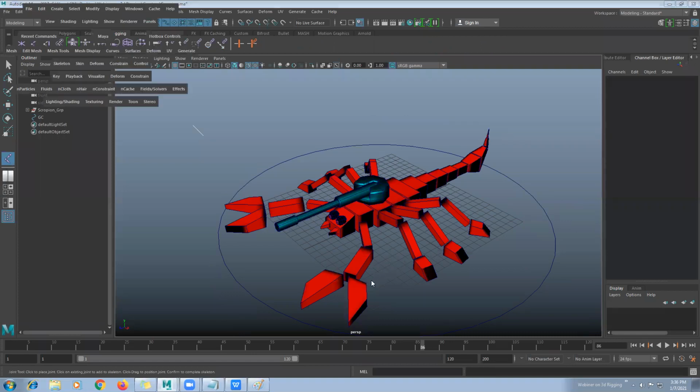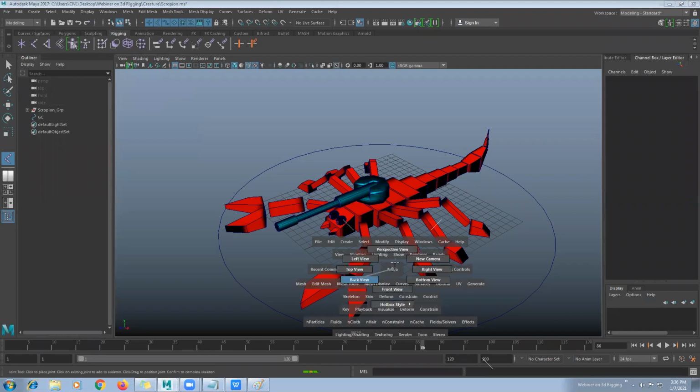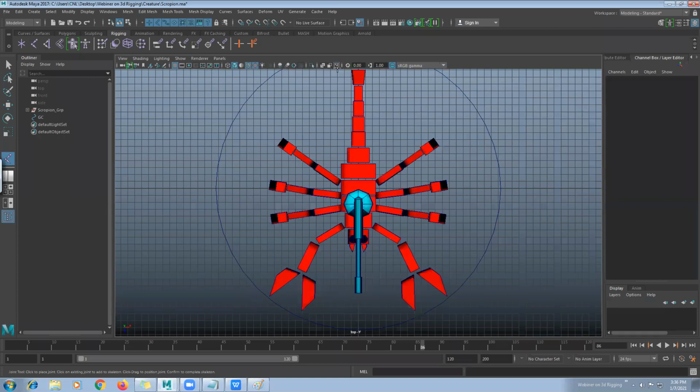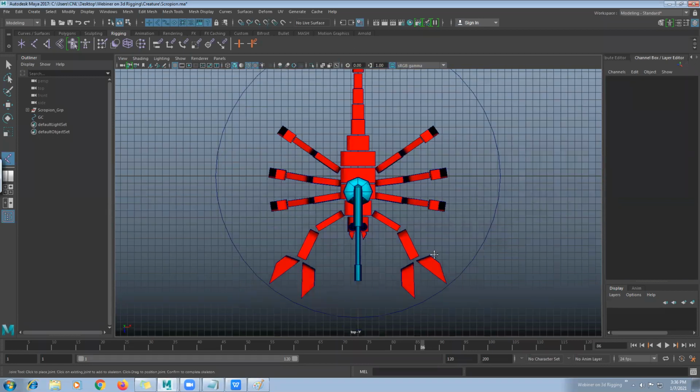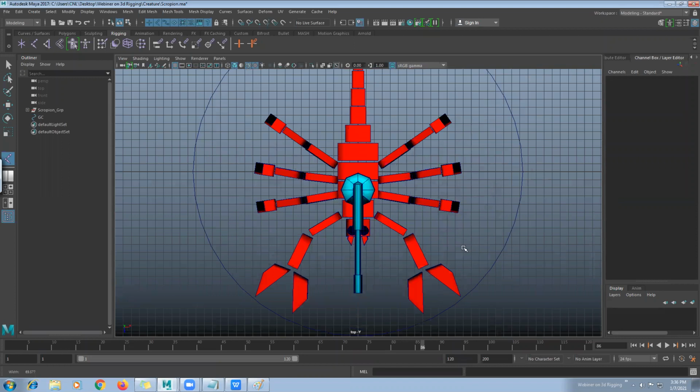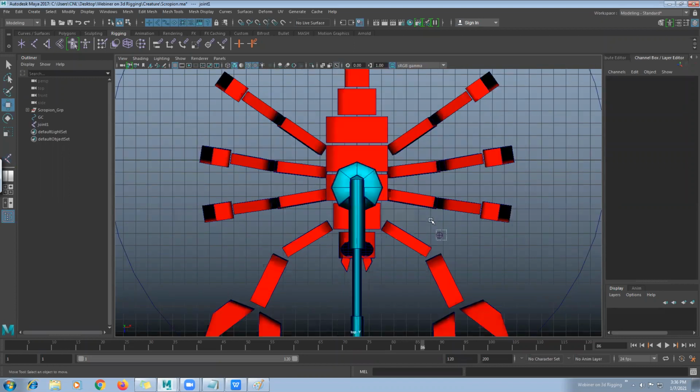So I go to the top view, which I believe is the best view, and definitely there is an option called extra joint that you should turn on, so that joints can be visible properly. I click once and hit enter. I don't need to click 2 to 3 times. If I click here in something like that way, we may generate a chain of connected joints.